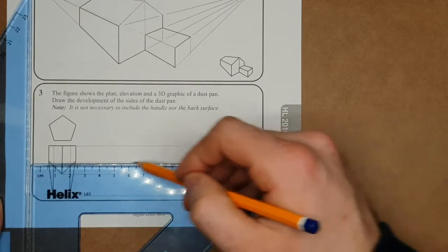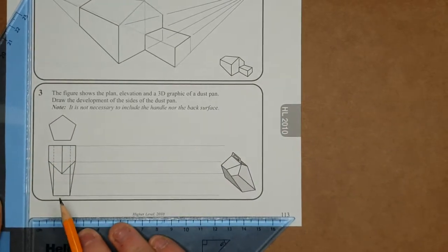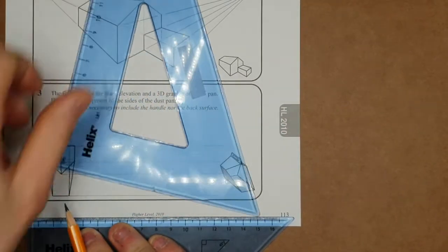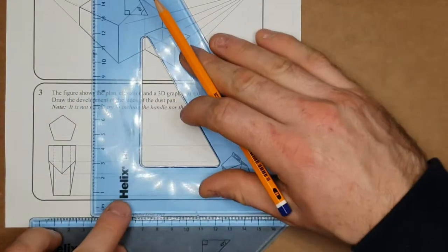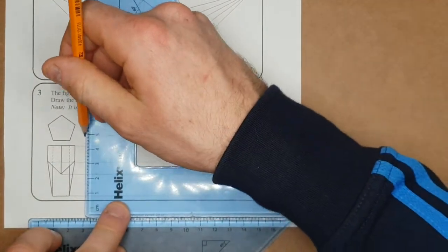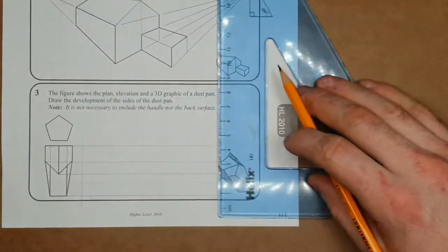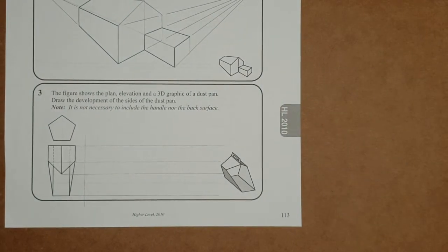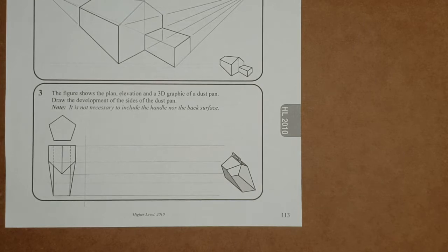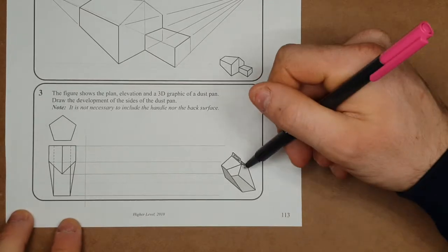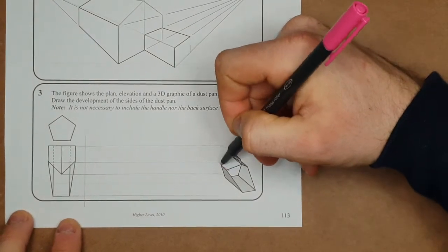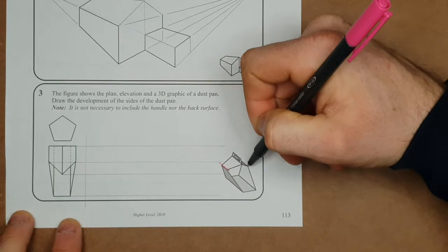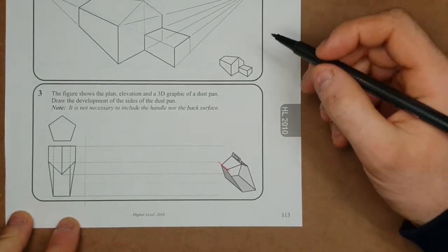And I just start off with a random position, let's just say there. A little bit of labelling will help me here. Now, we start off, as always with any development, with the shortest possible seam edge. Now, the graphic here is handy for that, so I'll be sending that one. I could use the one on the left or the one on the right. Either way, that's the shortest seam edge.